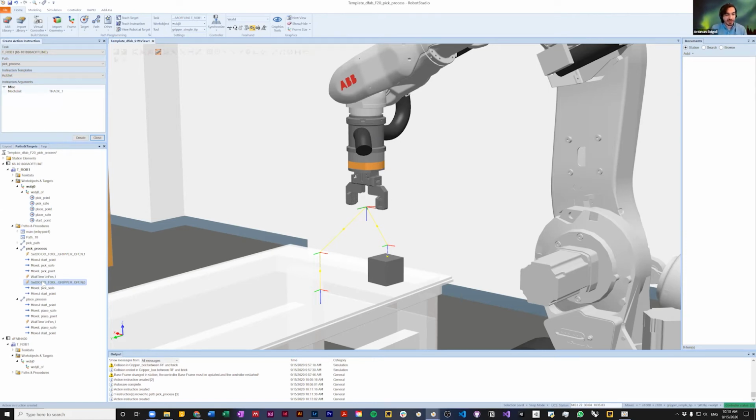It means that if you move immediately after this set DO, the robot tries to grab the object, like imagine that these fingers are moving slowly, but before the fingers are getting completely closed, the robot moves back. So we need to add another wait command right here after this set DO. And it's going to be pretty similar to this wait command that we had previously. So I just Control-C and Control-V here.